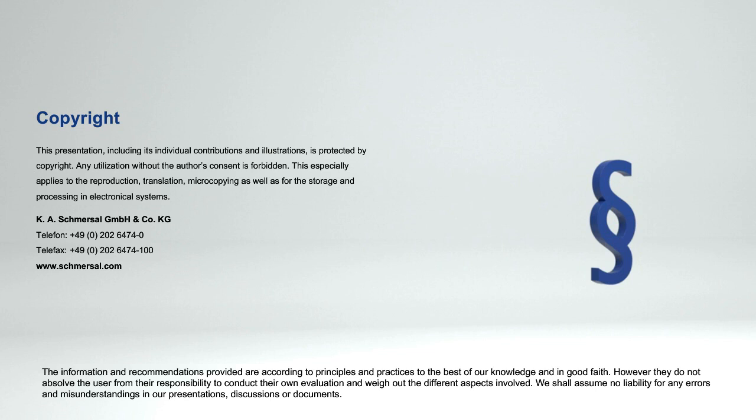Well, using these measures and the chances of a fracture occurring. When you look at performance levels or SIL levels, they're not saying that things can't happen, that it's completely impossible. It may be a very minute chance of certain things happening. What are the chances of it really happening? That's why we call it a PFH, a probability of dangerous failure per hour. What are the chances of that happening? So that's what we mean by fault exclusion. I simplified that a little bit. You can get into more details about it, but that's what we're referring to.